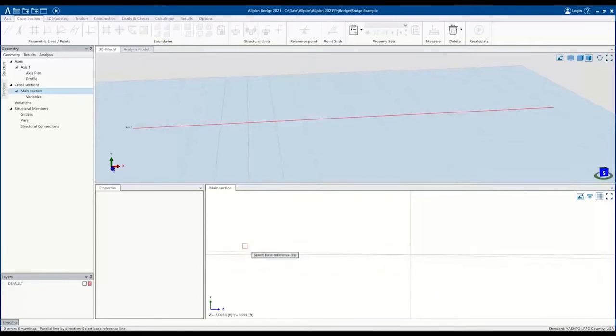So what these lines are doing while Jalpesh is working here is actually two separate purposes. One is to serve as construction lines in a CAD environment, give me an array of snap to points to connect to create elements. The other is that, as the name suggests, they're parametric, which means that right now we're entering fixed values to control them. A cross slope of 2 and -2%, deck thickness of a foot. We would then enter in girders shortly, space them at a fixed interval. All of those values, then we can go back in later on and edit.